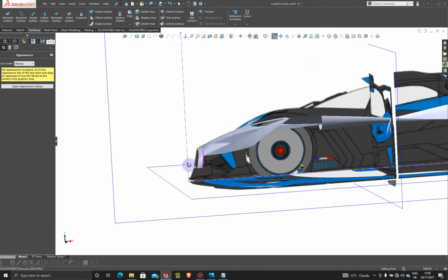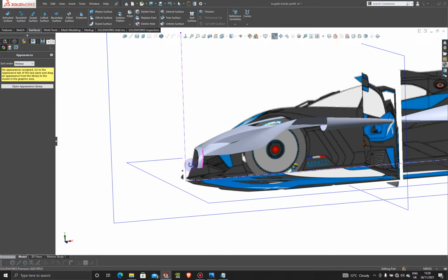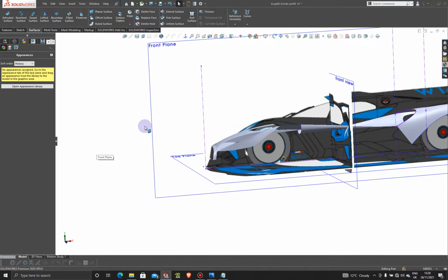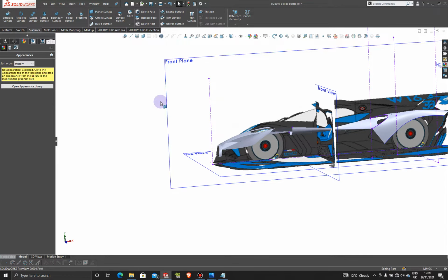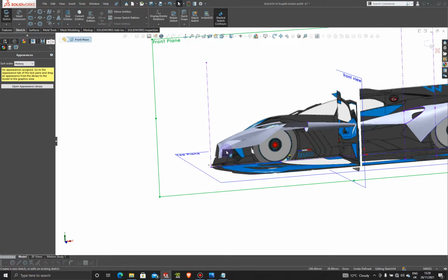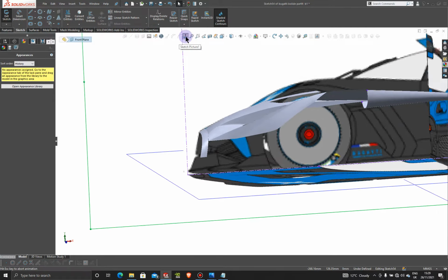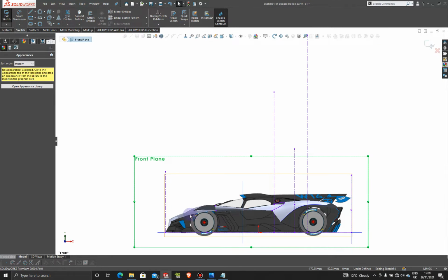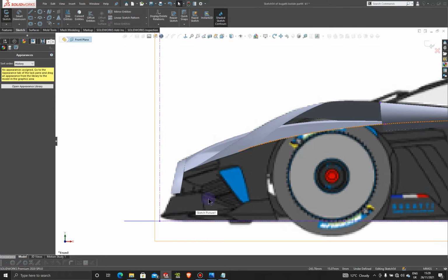And then what we're going to do is create a plane. So let's click on the front plane here, make a sketch on the front plane, press normal to profile. It jumps into profile, and we want to make a plane that comes in all the way here, so we can create these sections here.